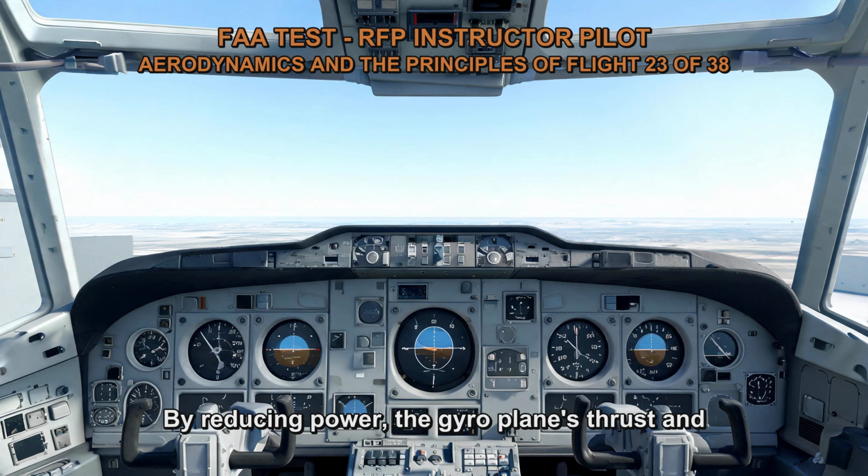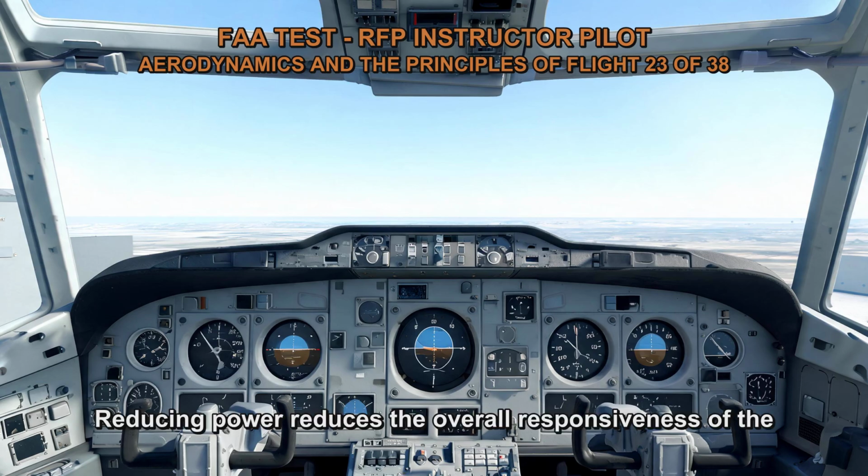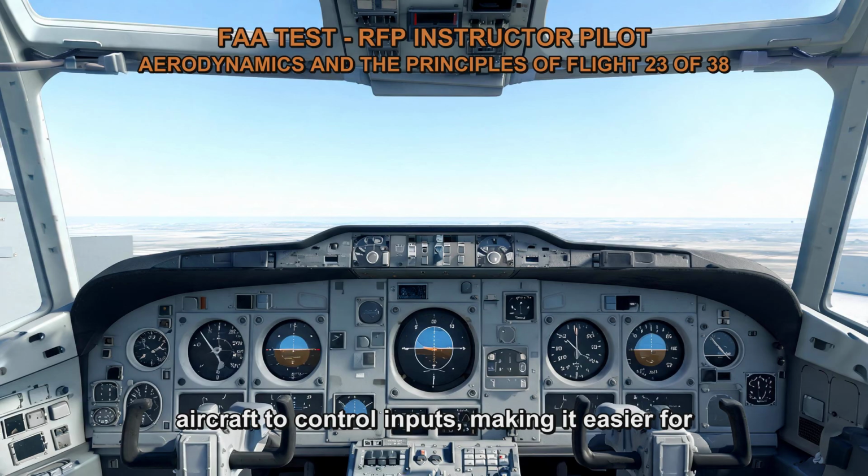By reducing power, the gyroplane's thrust and speed decrease, which in turn reduces the dynamic forces and aerodynamic effects. This helps to stabilize the aircraft and dampen the oscillations. Reducing power reduces the overall responsiveness of the aircraft to control inputs, making it easier for the pilot to regain control and prevent further oscillations.